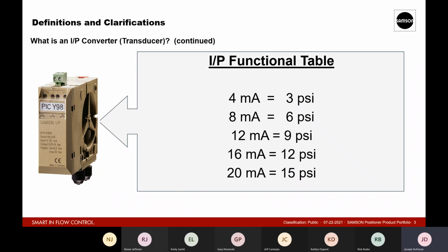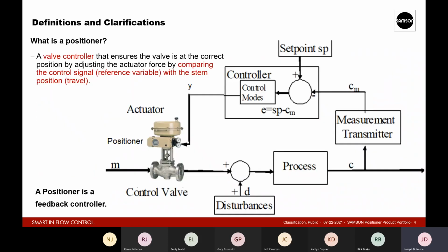If there is a difference in the pressure required to move the valve or a change in the frictional profile of that valve, the transducer cannot correct this offset. So the process control loop will be constantly trying to remove that deviation and achieve the controlled position that you've desired through the controller.